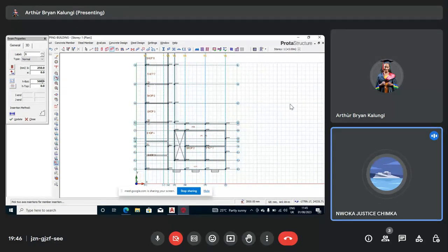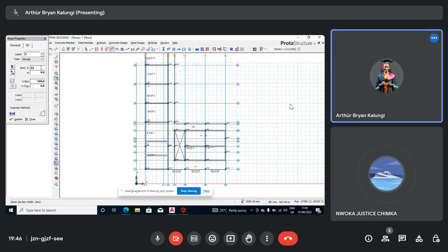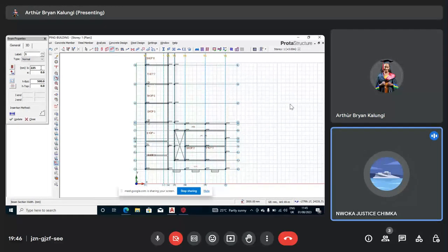Can you hear me? Yes, B is 225. And then put in your beam depth. That H bot simply means your beam depth. I told you before, in our first class, that your beam depth starts from 450. That should be your minimum. So put there 450 millimeters, 450.